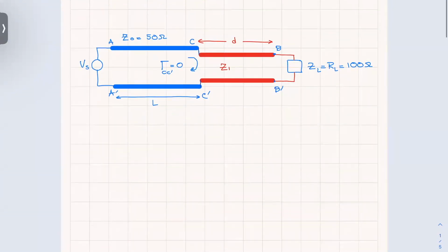So let's try to do that. Problems like this, you do not solve with a Smith chart. You remember I told you that when we are matching a load to a source, you will never use a resistive element. A transmission line is okay because it's not a resistor. A very good transmission line is not going to have losses that will be important to me.